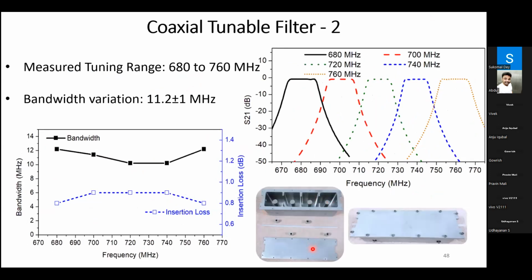So we built the filter using aluminum parts, and we used a commercial plastic for the dielectric rod. And we were able to get reasonably good measured performance, a reasonably good constant bandwidth criterion, and reasonably good insertion loss.